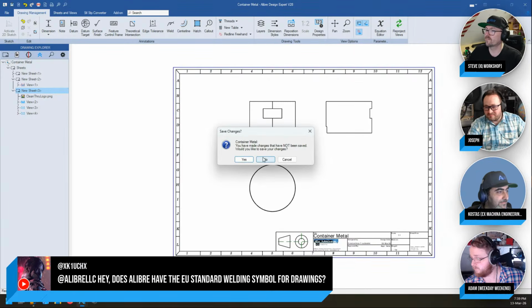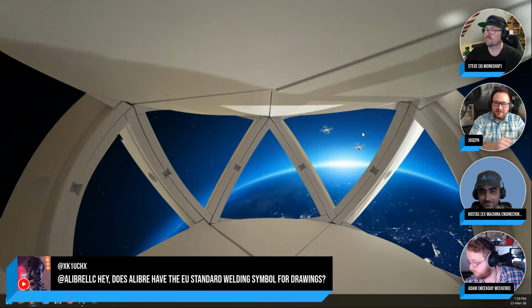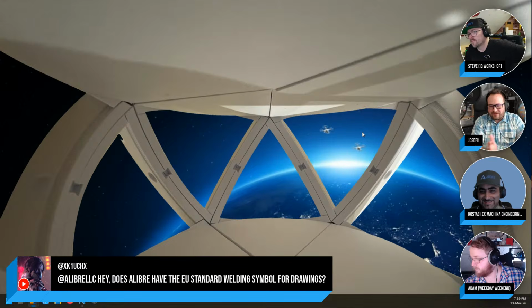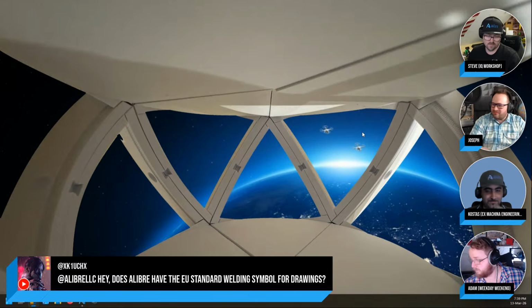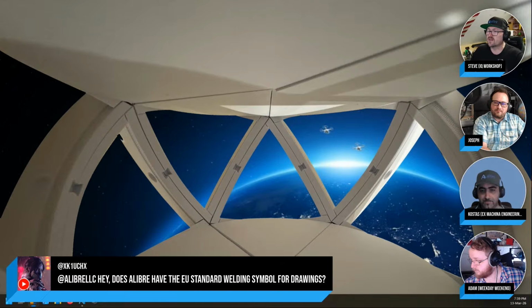That's a great way to present it. So as far as I know, with weld symbols, you have ANSI, you have ISO, and they're so similar, but if you flip the symbol, it means the opposite thing in some ways, but it gives you the way to build a weld symbol that has the ISO accommodation. So it should accommodate what you need, whether you're in the States or in Europe. And I'm guessing it's probably worth, if you're uncertain as to which standard to use, reaching out to the manufacturer that you're going to use and asking them the standard. I think that's always great advice. Yep. That's top.